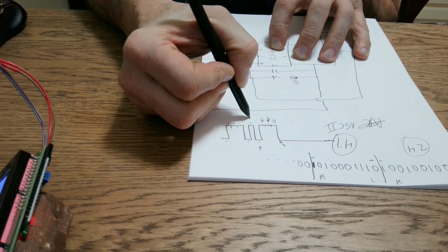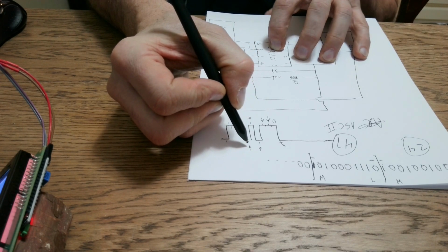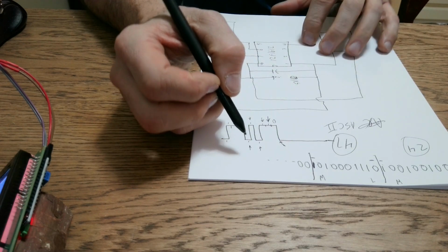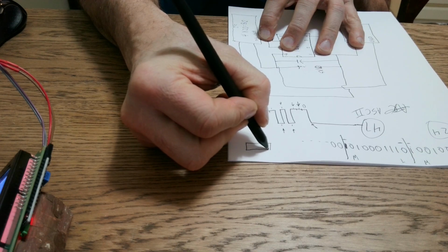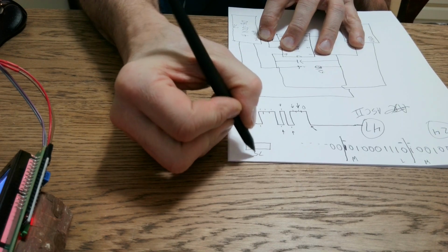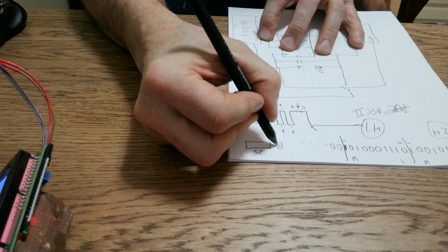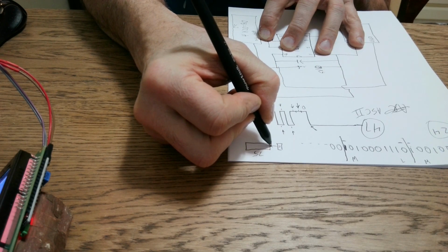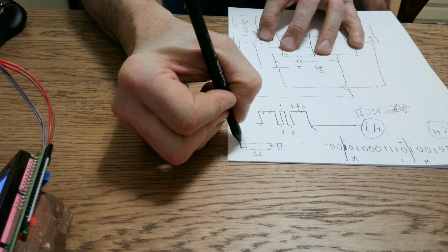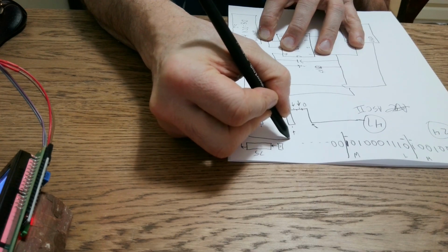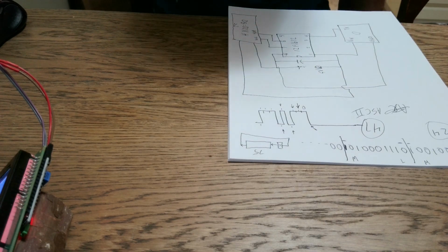And I will do this for 8 bits. I will then rotate those 8 bits into a register. I'm going to rotate it into register 75 because that's how I programmed it. So I'm going to rotate 8 bits of data into my register, and then I will put that, of course, somewhere in the memory, which I'll eventually take back out and throw onto the display.